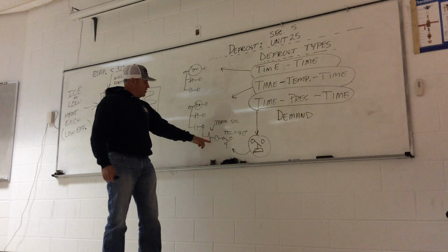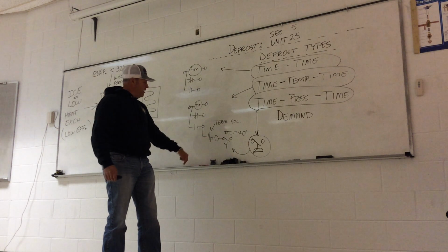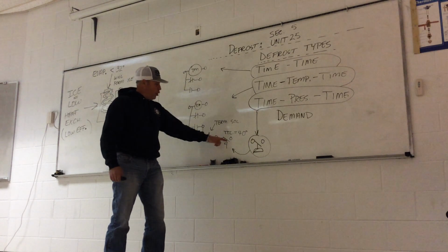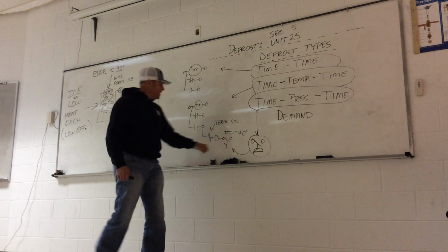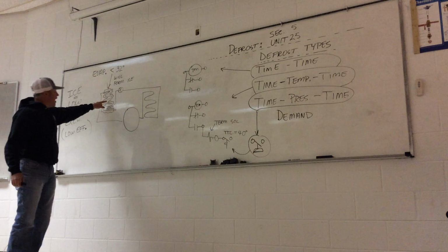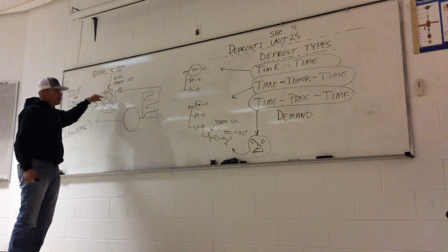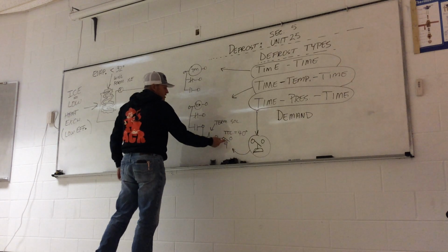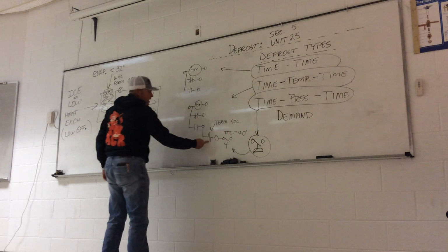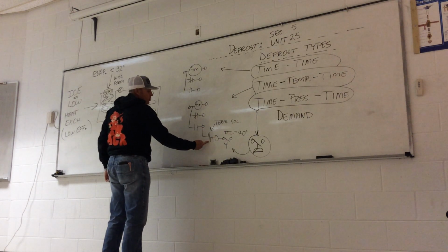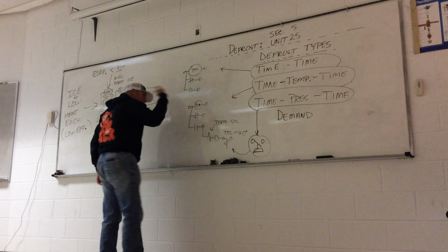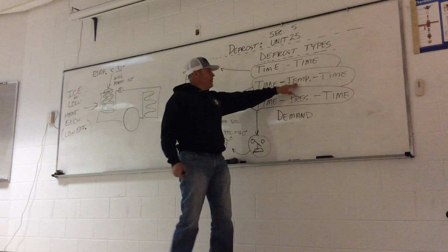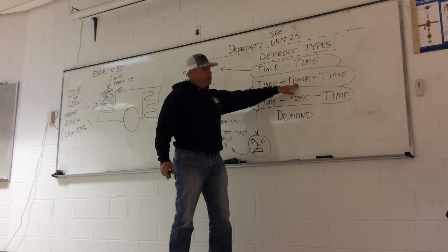And so we would use a termination temperature control wired in series with a termination solenoid. The sensing bulb for this temperature control would literally be right on the evaporator, submerged in there. And if we got up to 40 degrees, this temperature control would close, energize our termination solenoid, which would take us out of defrost. So time puts us in, and then temperature takes us out.